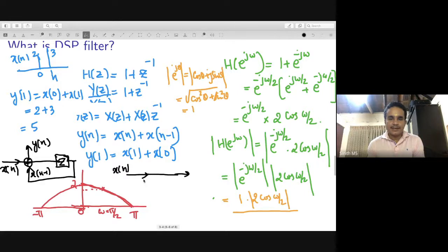This you give directly. Xn minus 1, you can get a delayed version from here, z inverse. Add it here. So this is xn. Xn goes here, you get xn here. And xn minus 1 you can get from here. You add it to get y of n.